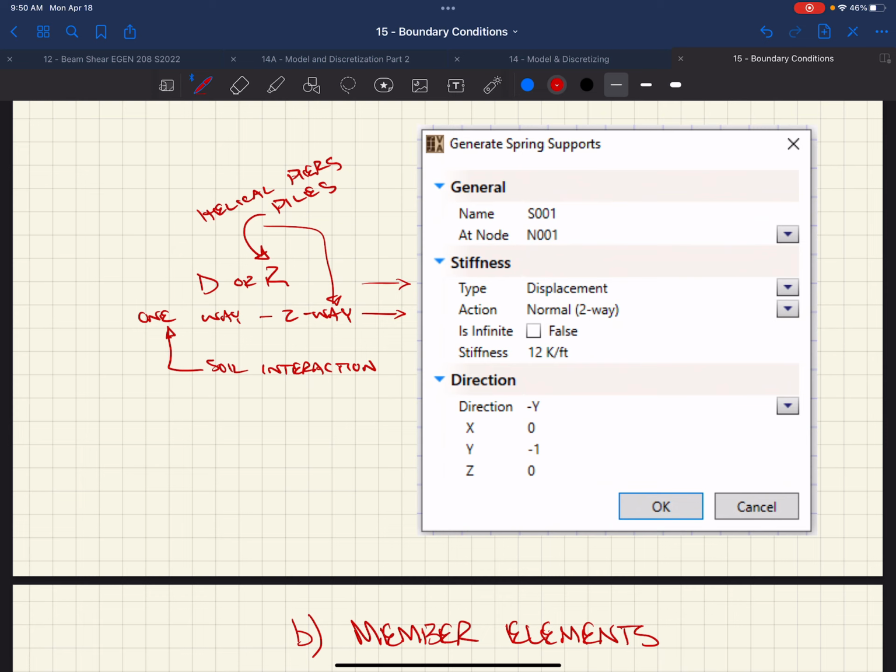So in certain cases, when an earthquake happens, the soils are actually moving. So you can ask a geotech for the lateral earthquake pressure. It's like, what is the soil going to be pushing on your foundation wall with? A lot of times you should consider that. Passive soil is a kind of measure of that to some level.